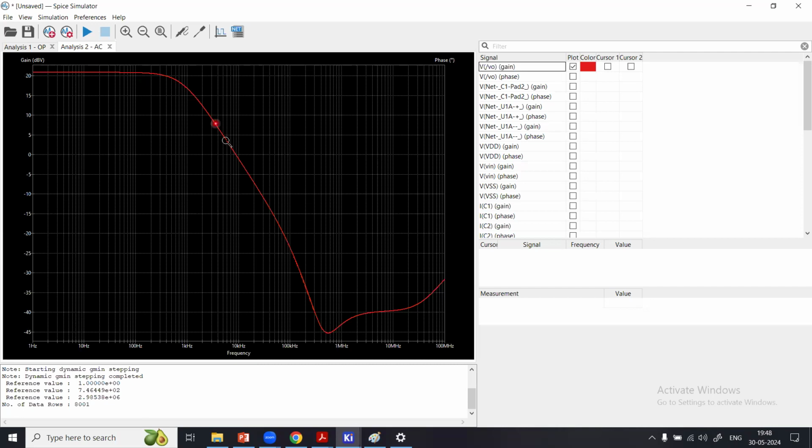So it's a low pass filter response, where you have got the dominant pole at about 200 hertz, at quite a low frequency. You can simply vary that also, because you have increased the gain, so your bandwidth is reduced, obviously. From here to this point, about 200 hertz, you have got the pass band, and after that gain starts dropping at the rate of minus 40 dB per decade. And then here you have a stop band of about minus 45. In fact, this is a cutoff frequency, the point which separates your pass band and the stop band.